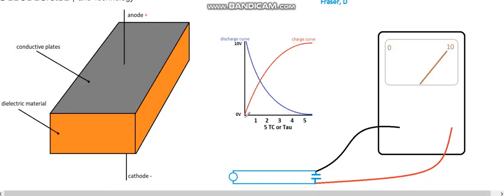But a capacitor will always sort of hold a charge, and it's because of this characteristic of the capacitor, where when a capacitor starts to charge, and this picture doesn't do it justice, it really charges within its first time constant, or tau, about 63% of its capacity. And effectively by its fifth tau, its fifth time constant, it's effectively charged, but it never really will get to 100% because it's exponential. It'll get to 99.999% or so of its charge.